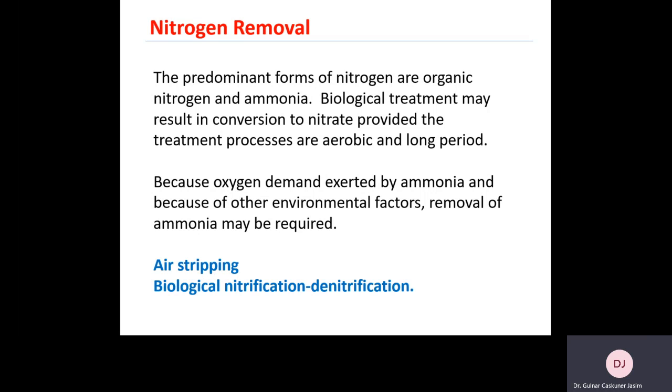Because of oxygen demand exerted by ammonia, and because of other environmental factors, removal of ammonia may be required. If we don't remove the ammonia, which is already present in the sewage, and discharge it to the receiving aquatic environment, that means this oxidation will happen in the aquatic environment, and most of the oxygen will be utilized, and oxygen deficiency will happen in this environment.